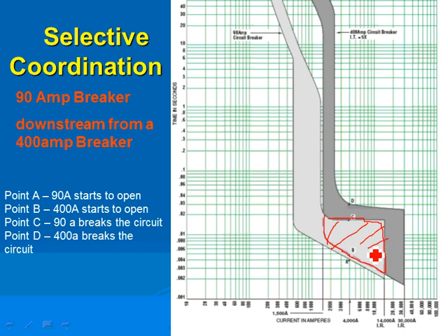In this area, that's only what did they say? Only 15% of the time when you have a solid three-phase. So 15% of the time, if you have a solid three-phase, you might not coordinate here. For 85% of the time, you have what? Ground faults, and you're fully coordinated. And that's as good as you can get on a